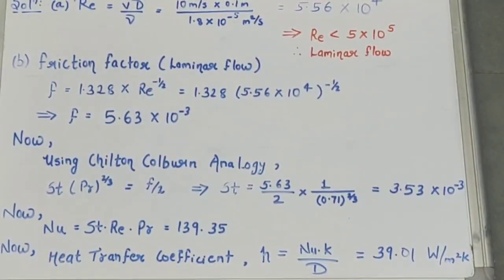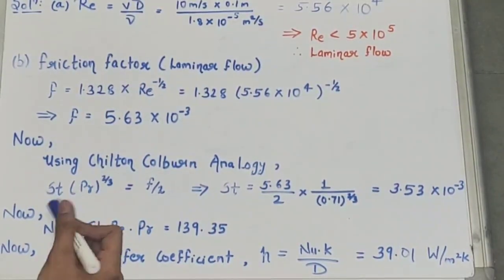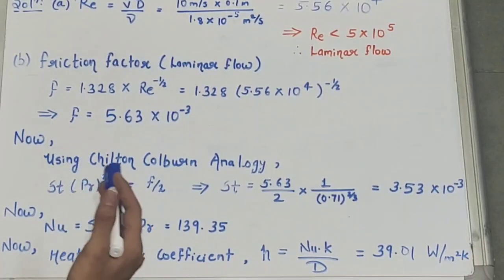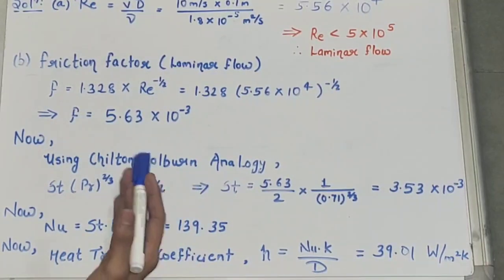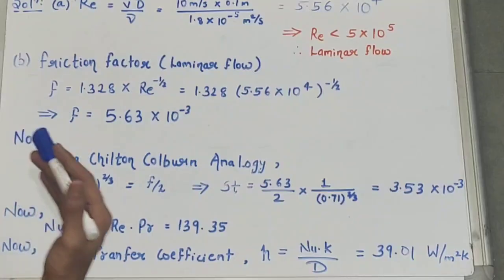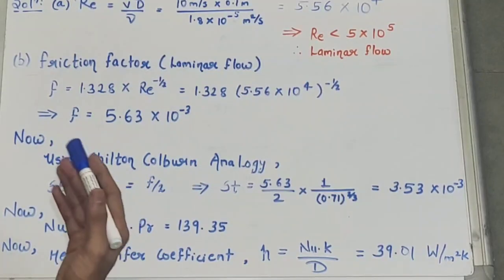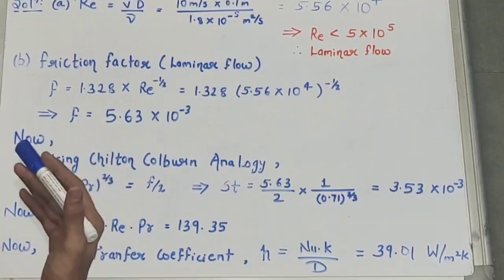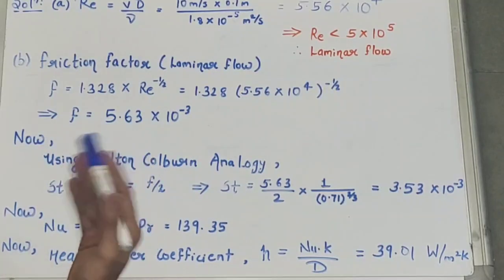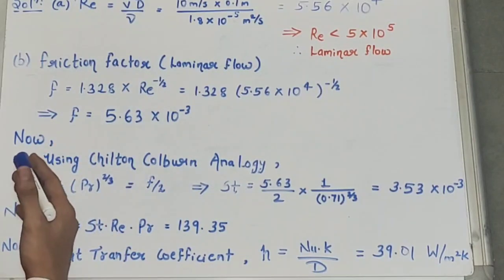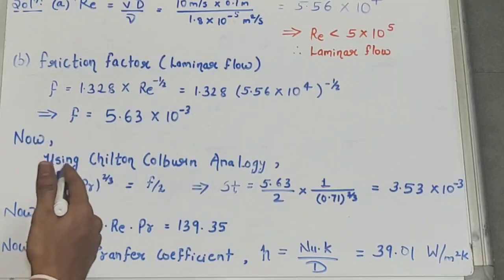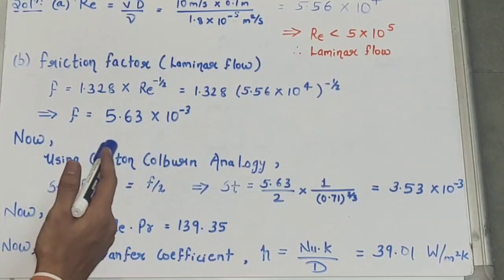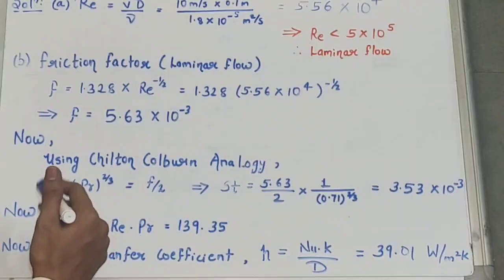So I am sure that you must have definitely understood what the problem is, what are various doubts related to it, the given data and the questions asked. So the first part of the question is to calculate Reynolds number. Now by this time you must be very familiar with what is Reynolds number and its formula. Reynolds number is given by Vd by nu. V stands for velocity, d is the diameter and nu is the kinematic viscosity.